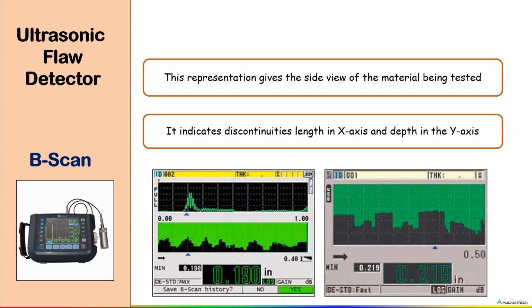The thickness is plotted as a function of time or position, while the transducer is scanned along the path to provide its depth profile. Correlating the ultrasonic data with actual transducer position allows a proportional view to be plotted and allows the ability to correlate and track data to specific areas of the part being inspected.